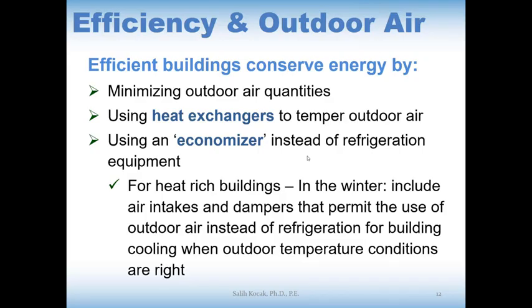Enthalpy controlled economizers evaluate both outdoor temperature and humidity. Don't forget, it is enthalpy controlled. Enthalpy is latent and sensible heat. That's why they assess both the outdoor temperature and the humidity, then mix appropriate quantities of outdoor and indoor air to achieve comfortable conditions without doing any refrigeration.